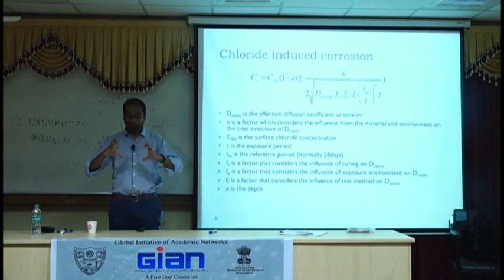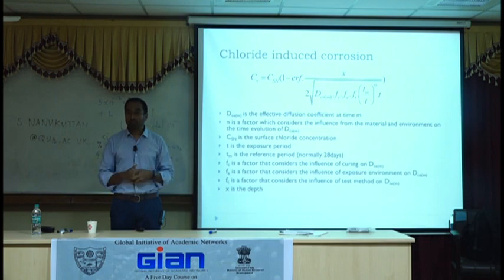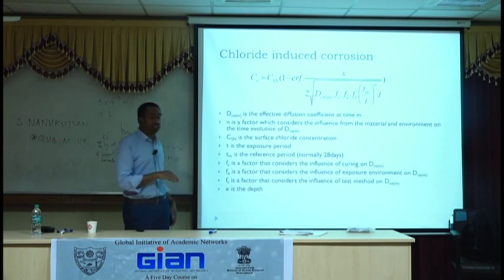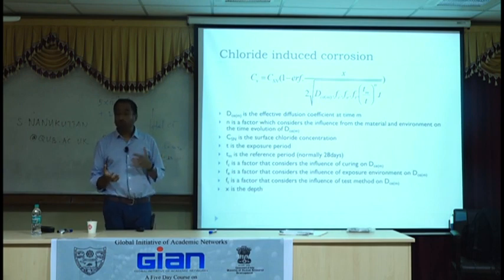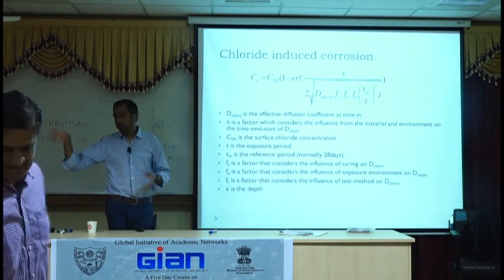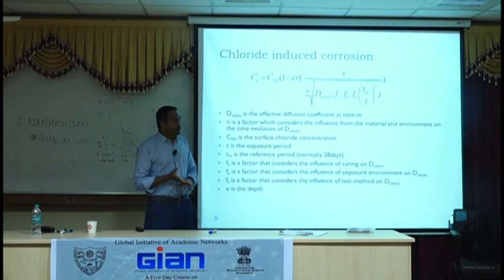Concrete has the ability to cure itself because you would normally add enough water in the mix anyway. According to Neville, a 0.26 water binder ratio is all that you need for curing. So if anybody says their water binder ratio is 0.2, I don't know how realistic that is. 0.2 is extremely low. It shouldn't really happen because it's not a workable mix unless it's heavily chemical based. So 0.26 is what you need. I prefer anything close to 0.4 because engineering-wise that's more reliable. I can spray it, I can mix it, I can flow it, which means it has enough water.